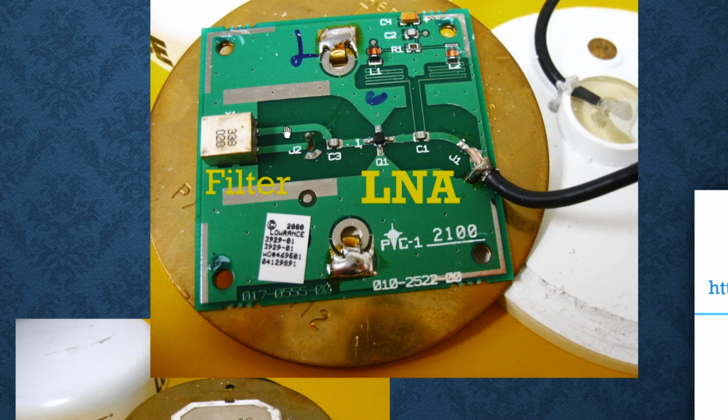And then it goes through a DC blocking cap because it's going into Q1, which is not really just a transistor. It's a monolithic microwave integrated circuit kind of thing that requires power. That actually comes up through the coax. And then there's a DC block, so it doesn't go anywhere there. It goes up here through the squiggly line, which is some inductance. There's more inductance here, and then there's capacitors. So that is filtering out RF, preventing RF from taking this path.